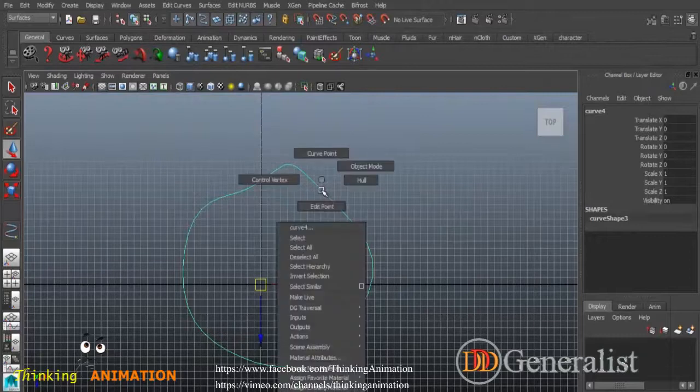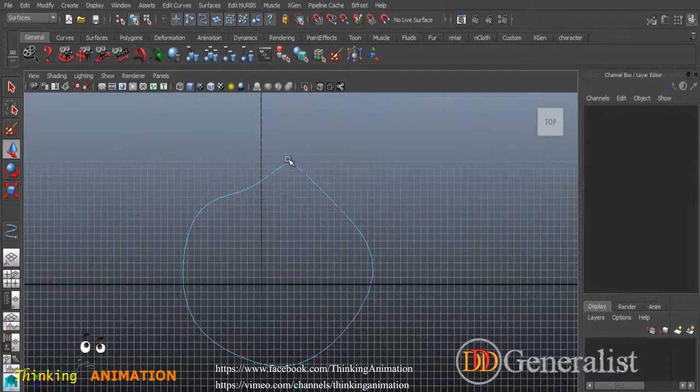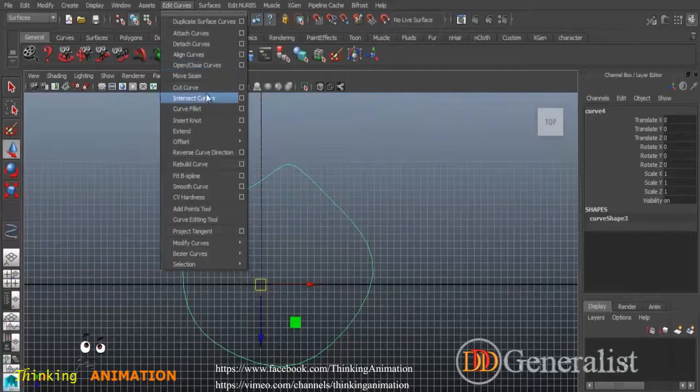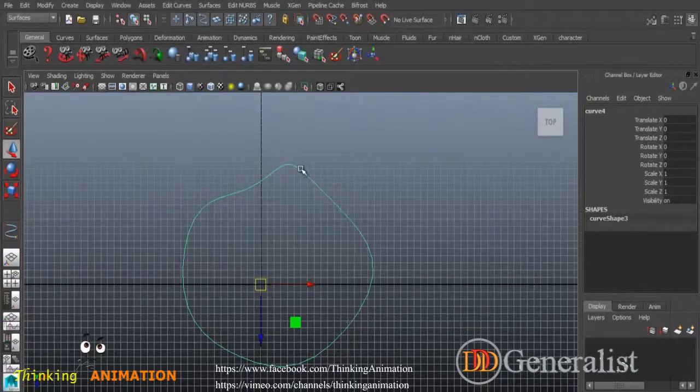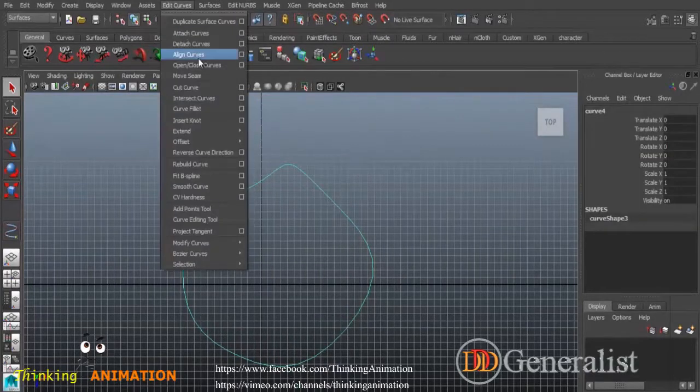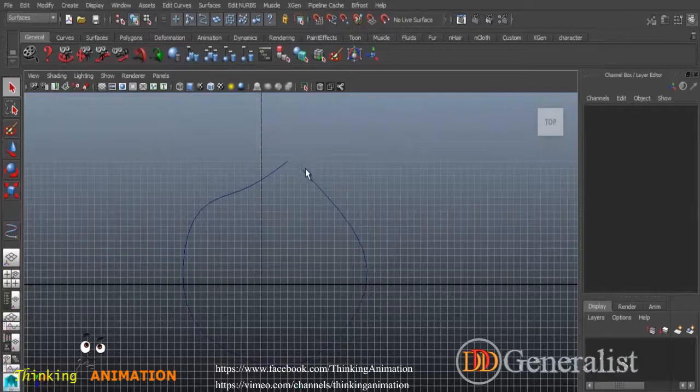And once you have a close shape, you just select the edit point, or select this line, and click open. It's going to open this one. If you select and choose any point right here and click open, it's not going to open from that point, because it needs to be first close and then open. So you select this option and click here, and from where the first start point was, it is going to be an open shape right from those points.